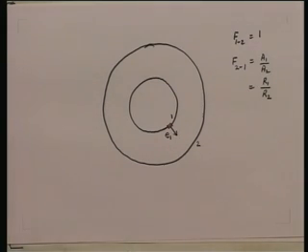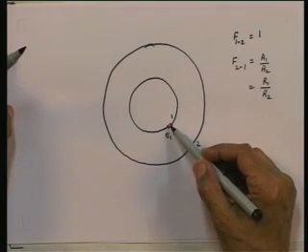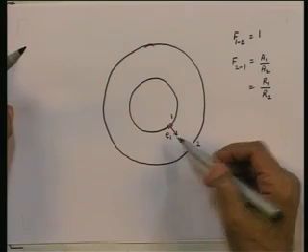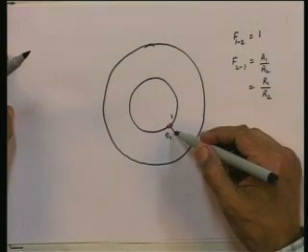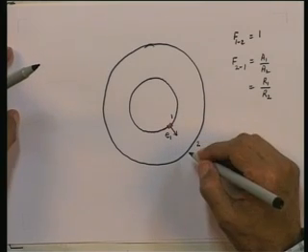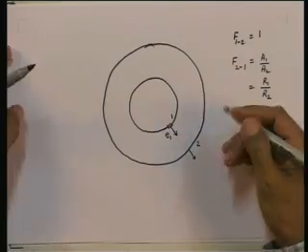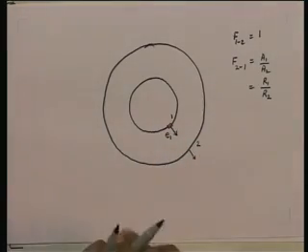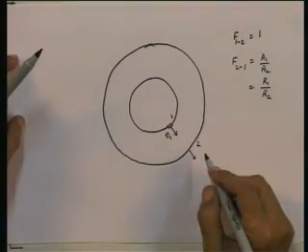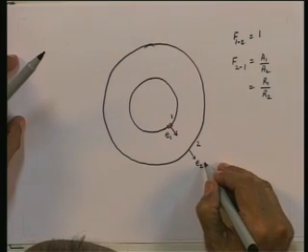So, now let us go back. Let us consider the radiation emitted from this element. E1 watts per meter squared are emitted. When all this radiation emitted in all directions of a hemisphere reaches the surface 2, the amount that is absorbed here will be epsilon 2 E1.